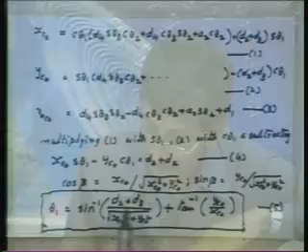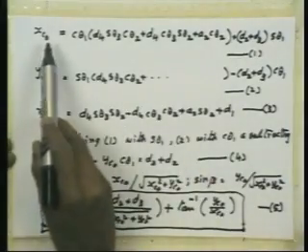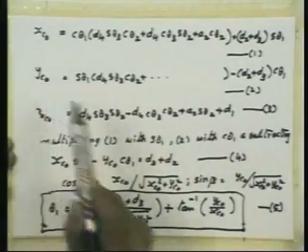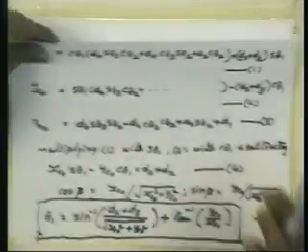So, argument of sin inverse not being within the allowed range, what does it indicate physically? This is another thing that one has to understand. Yes, it is beyond the reach, but beyond the reach where? So, if you look at what we had used, x0 and y0 are the projections on the xy plane of the global frame, right. So, we are looking at the manipulator in that projection. Okay. So, let us see the manipulator in that projection.